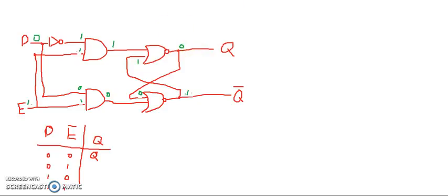Okay, that makes sense. What if we have different values? What if this one was a 1? Then 1 propagates here. 0 and 1 becomes 0. This becomes 0. And 1, 0 becomes 0 again. And you're saying, wait, this is a problem. They can't both be 0. Well, 0 propagates back down, and this becomes a 1. So this will eventually stabilize, because if 1 comes here, then it's going to output 0, and then when 0 comes here, it's always going to output 1. So as we can see, we set 0, 1 to 0 all the time.